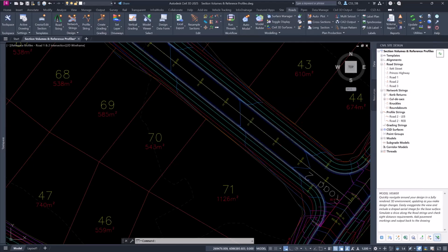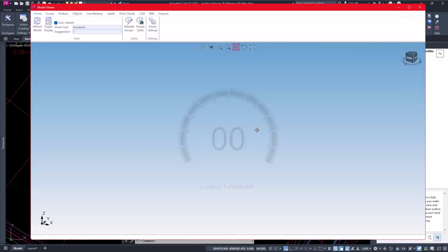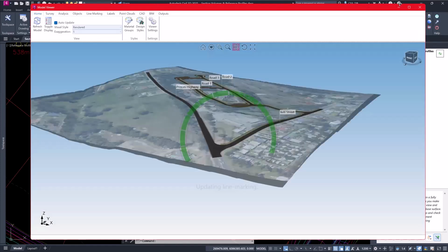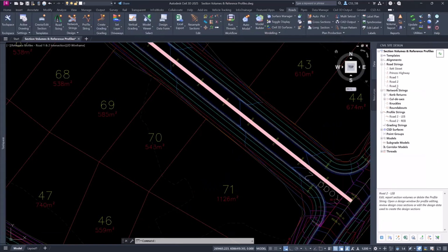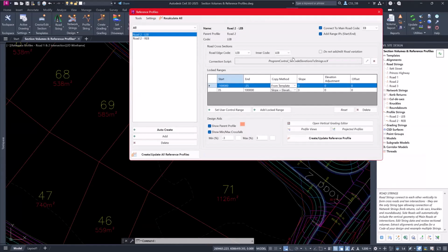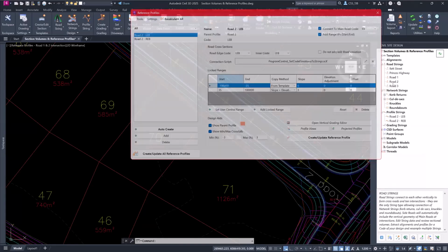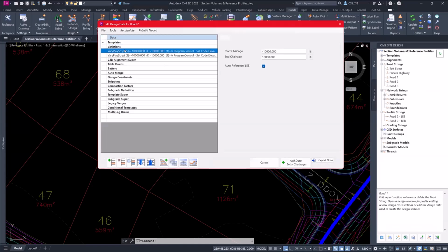There was just one question that came in with regards to how this is being applied in the design data form. Yeah, good question, thank you. In the interest of time and trying to hit our timelines, I skipped a bit. The way the software manages it is in that form in here. It's using a script X to generate the overrides in the cross section. If I look at the design data form for Road 2, you'll see a couple of script variations in here, which are all auto-controlled by the software.